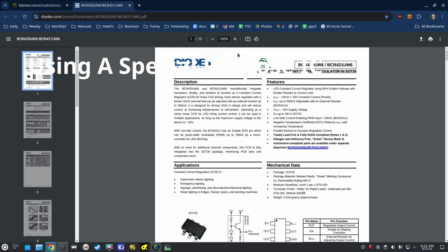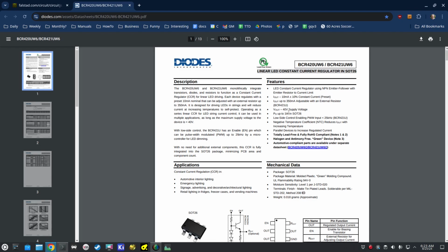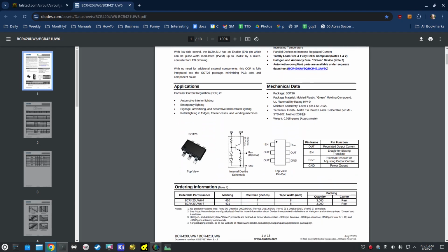They actually sell this chip. Here's one of them. They sell many, of course, that basically puts all of the parts into a chip to make it convenient. Instead of a Zener, they use 2 forward diodes, which in this case makes a lot of sense because these will be temperature coupled, which we'll talk about in a minute.